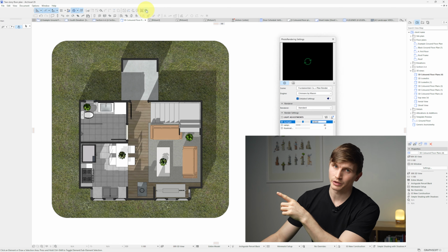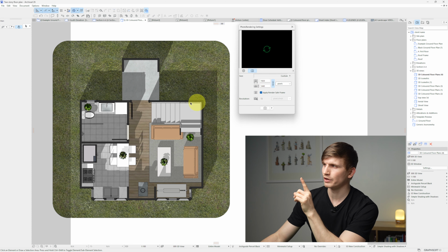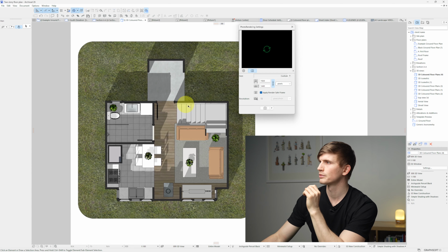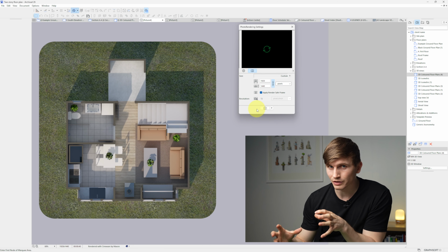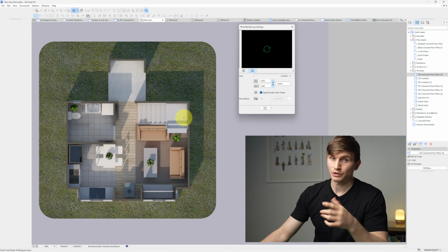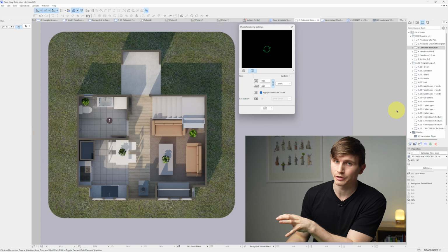From here, let's go to our photo render settings. I'll select the preset that we've got for the floor plan. I'll apply the render save frame. I'll bring this one just across. So now when we hit the photo render projection, we can share a nice detailed render of the inside of the room, which we can just copy and paste onto our layout. And after that, we can put extra notes onto the floor plan for even clearer presentation.